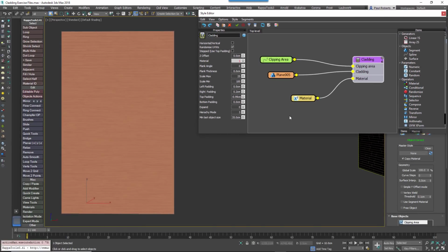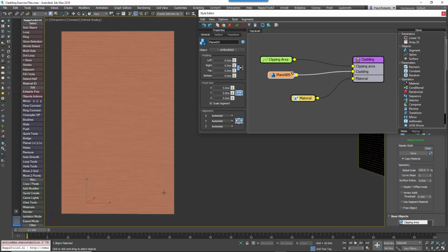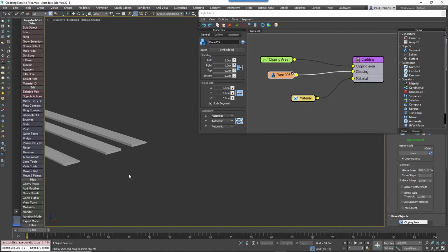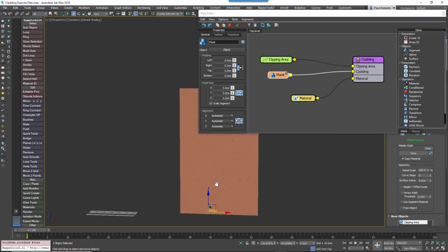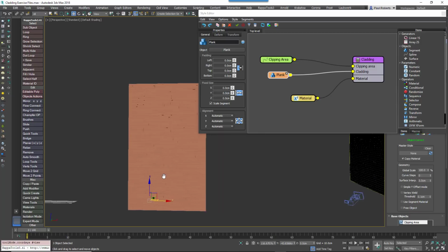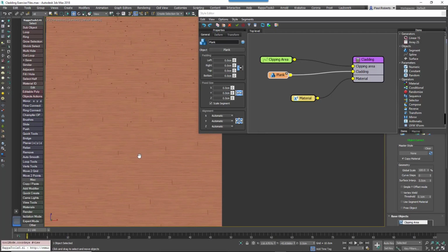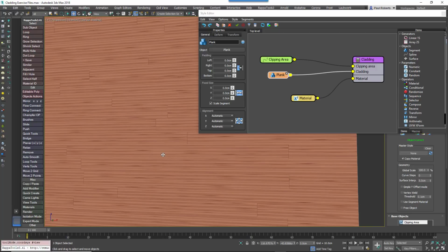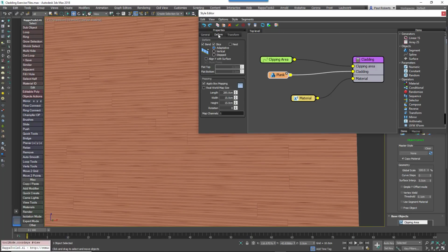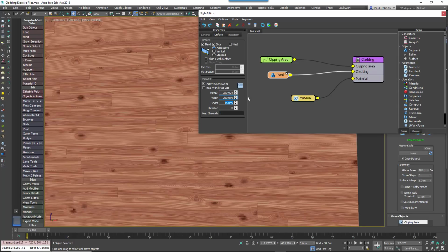The first thing you might want to do is to change the geometry itself. To do this, just select the segment node and choose New Geometry using the button from the Properties panel. In this case, we'll pick a simple straight-edged plank. If you've added your own materials, you might want to change the UV mapping. To do this, go to the Deform Mapping Settings and enter new values for the length, width and height.